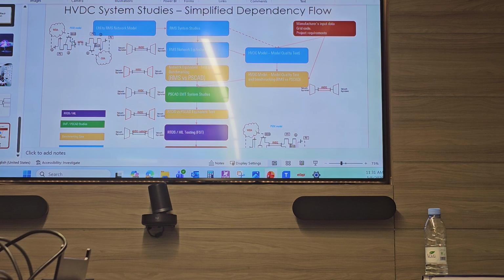So if you simulate load flow and open breakers somewhere, you will see how the load flow goes. If you do it in reality, it's not the same in terms of amps, but it's very close within these tolerances. So if they match, this is a sign that we have done a good model, and it represents our HVDC system.